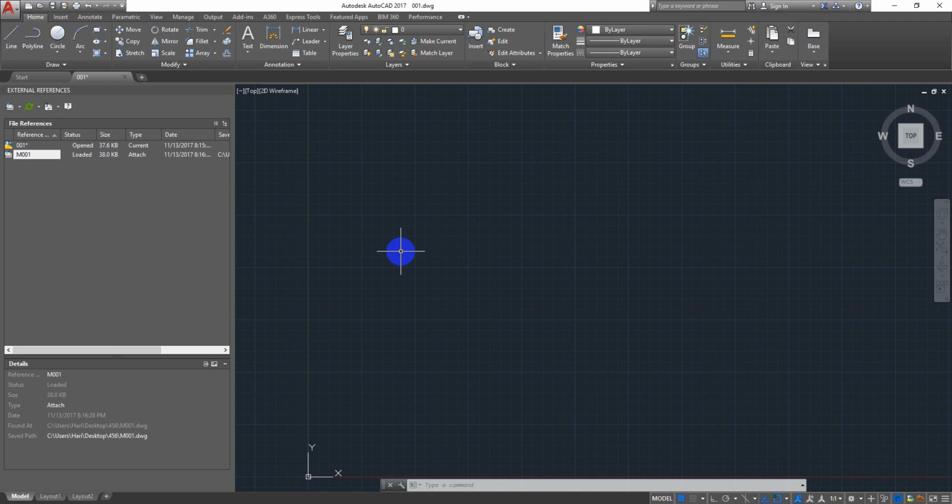So first you have to prepare the grid. That should be the first file you create for any project. Then you xref that file into a blank file with 0,0,0 as the origin point. That is also very important because it very much matters where exactly you put this drawing and work.